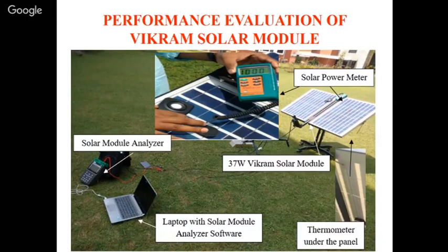After doing it outside, because when we want to do the MPPT, all the algorithms, P&O, incremental, GA, PSO, whichever algorithm you are doing, have to be compared under the same condition, the same irradiation and temperature. Only then can we compare. If they are at different irradiations or different temperatures, there is no use in comparing. That's why doing it outside in the field is very difficult. It will be cloudy, or suddenly sunlight will come. So it was very difficult to do the experimentation outside.